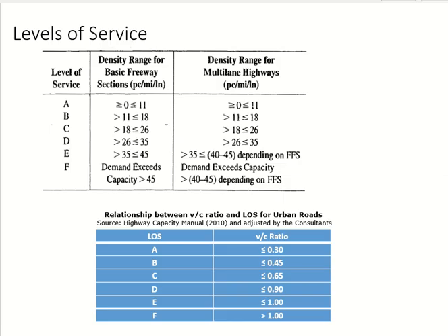Okay. So the weather conditions did not change the level of service. So the overall traffic is still the same. But that doesn't mean everything is the same. You see the free flow speed has reduced. So the weather conditions will reduce the free flow speed. So even in free flow conditions, our drivers will go slowly, which makes sense, right?